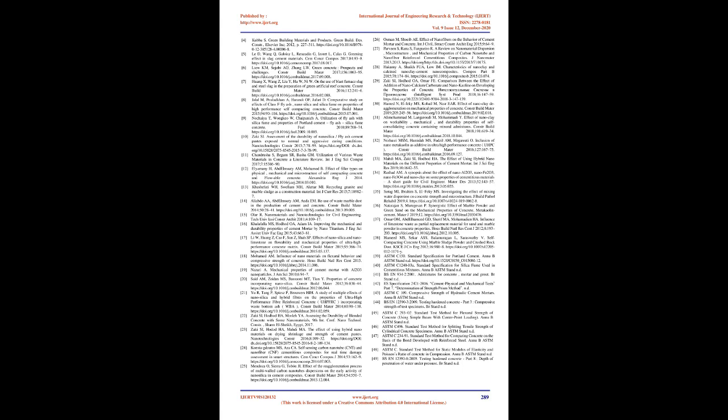5. Conclusions. Based on the experimental results shown in the study, the following conclusions were obtained. 1. Sprinkling after stirring dispersion technique represents an effective and practical means to overcome the NC agglomeration problem in concrete mixes. 2. Using different ratios of hybrid additions as NC, as cement replacement, and MP, as sand replacement, in normal strength concrete enhanced the compressive strength.